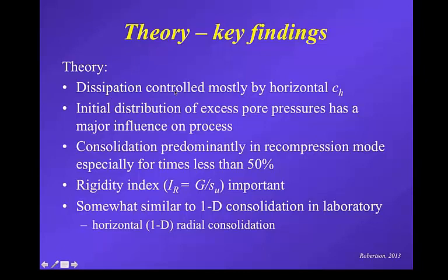And then in the late 90s, Professor Mayne, with one of his students, Susan Burns, developed another solution, also based on cavity expansion, but this time combined with a critical state soil mechanics constitutive model. And probably the two most significant works are these latter ones, Houlsby and Teh, and Burns and Mayne. So those are the ones I'll briefly talk about.